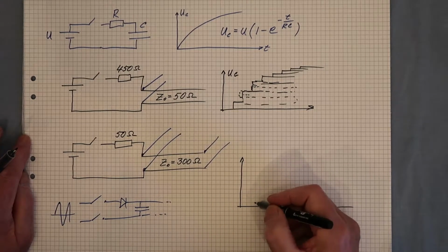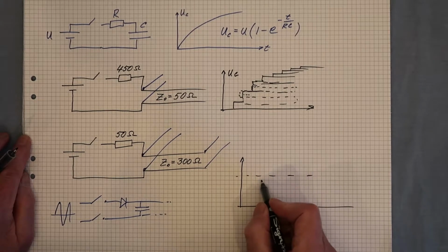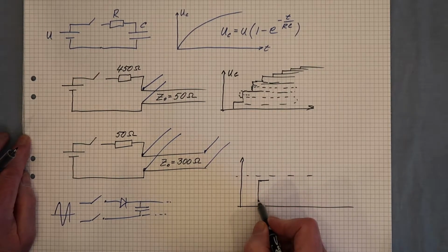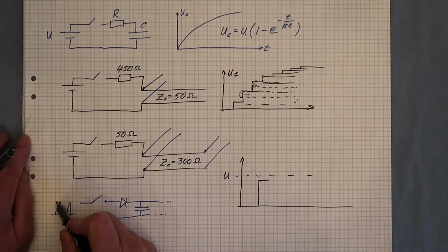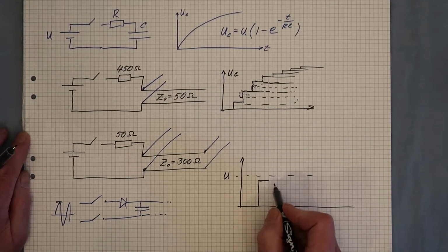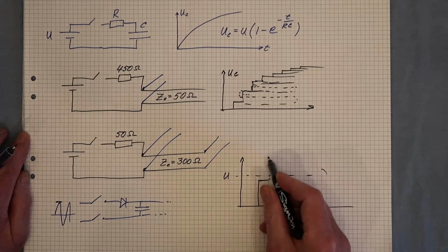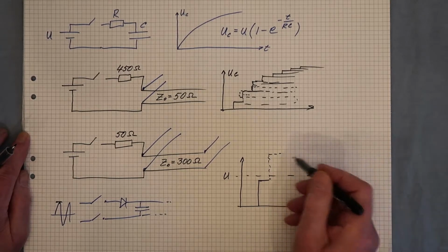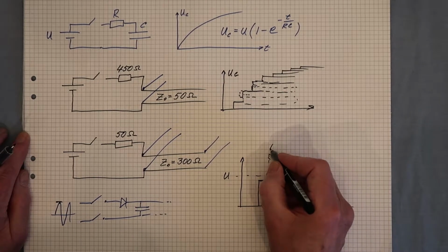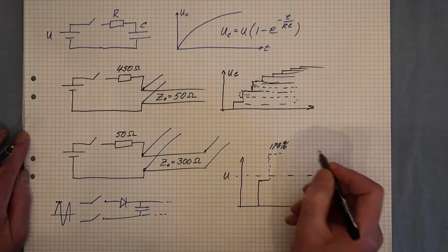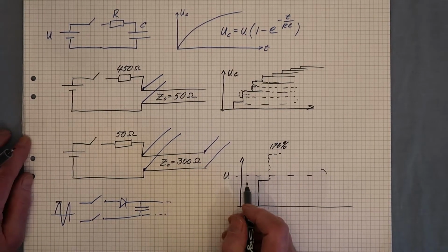We saw that the first step was actually 85% of the voltage, for instance over here. And this voltage goes out and is reflected back. So the top voltage within the capacitor will be 170% of the mains voltage, of the generator voltage.